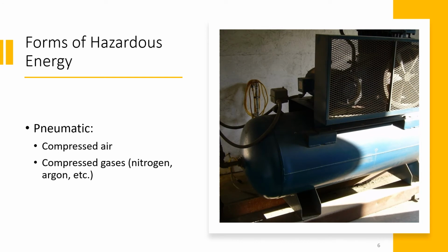Pneumatic. This is typically found in the form of compressed air at an industrial facility. Sometimes the compressed air is also dried, so they may dry it to a -40 dew point. But it's not uncommon to find compressed gases in more of the high-tech manufacturing out there, because nitrogen is not introducing any form of oxygen, any form of water. It does a really good job of driving all the internal valves and everything. So that is something that can be found in the more high-tech environments.